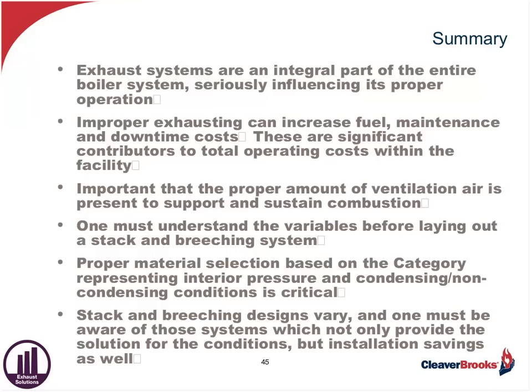Well, I can handle that one, Chuck. I think if you're looking at, let's say, anywhere from a 1/16 of an inch to an 1/8 of an inch of soot on the heat transfer surface of the boiler, you're going to see some elevated temperatures. You're going to see the temperature of that stack rise quite predominantly. Exactly what is it going to equate to?